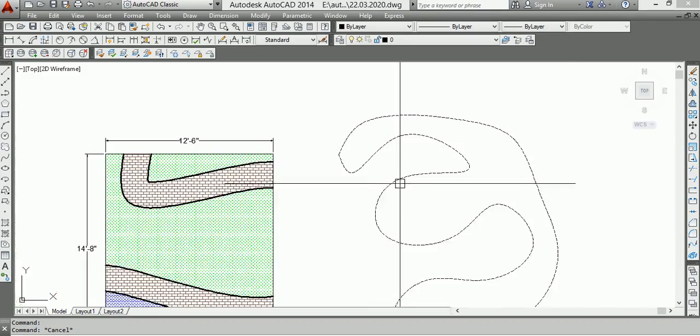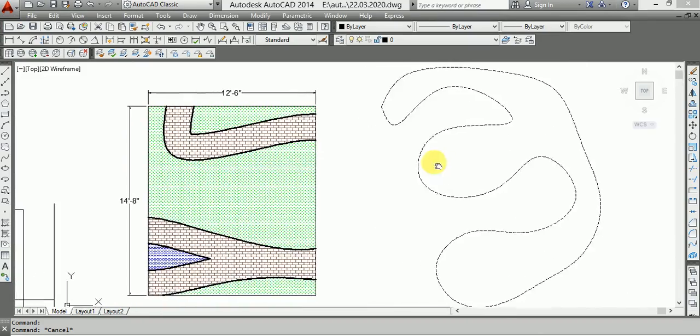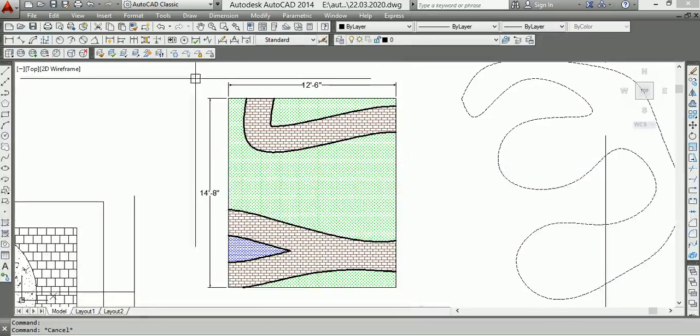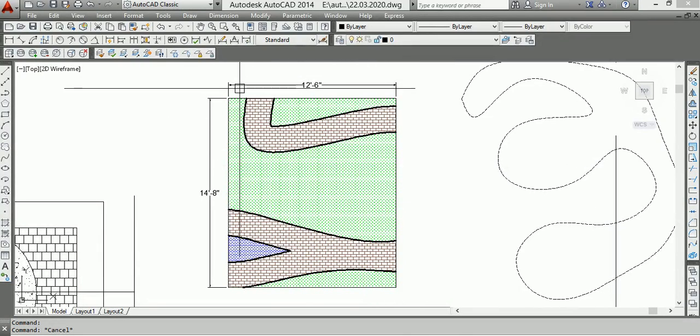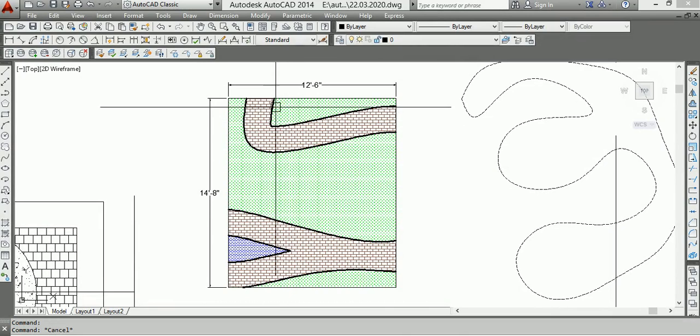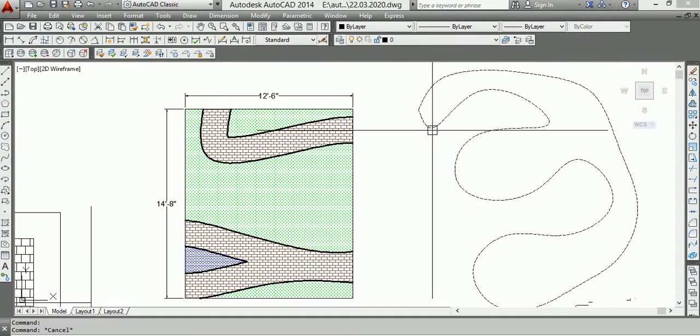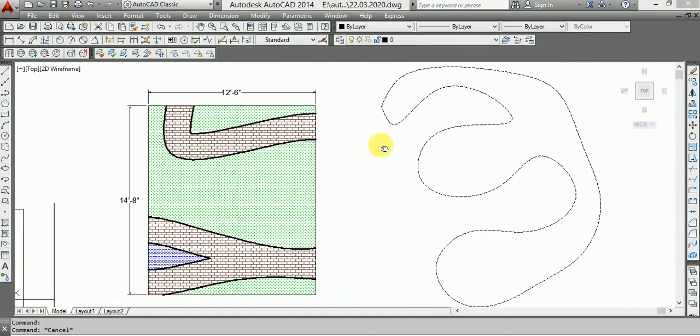Okay, this is all for today. So think about a drawing like this and try to draw using the line command, spline command, offset command, hatch command, and dimension style and line color control thickness. Okay, so this window you see now will be your task for today.